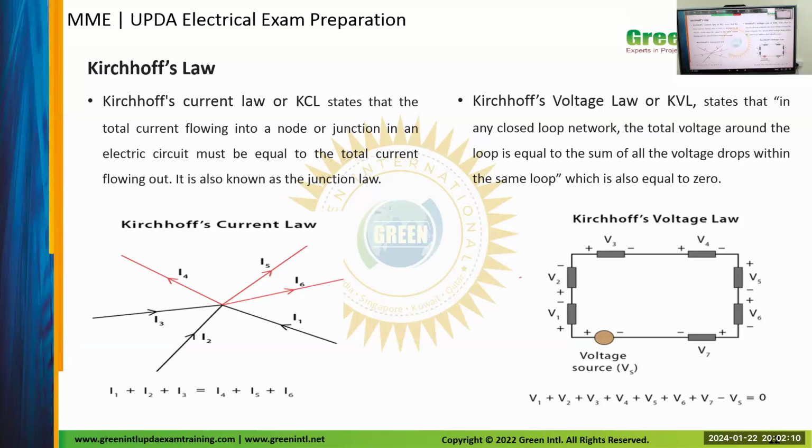Now we discuss the Kirchhoff's laws. We have two laws: Kirchhoff's voltage law and current law. As I told, in our exam they don't ask for the definitions, we just need to remember the concepts. Usually, for the current law, the important thing to remember is the node. In your circuit, if you see a node point, we can apply Kirchhoff's current law. And if you have a closed circuit, we can apply Kirchhoff's voltage law.